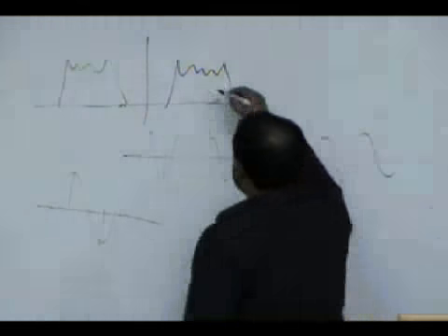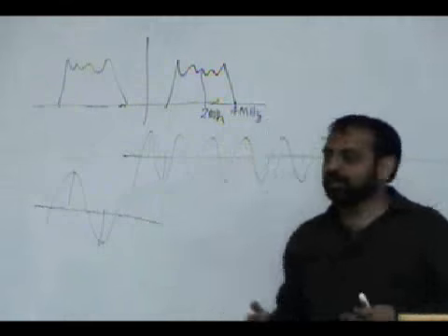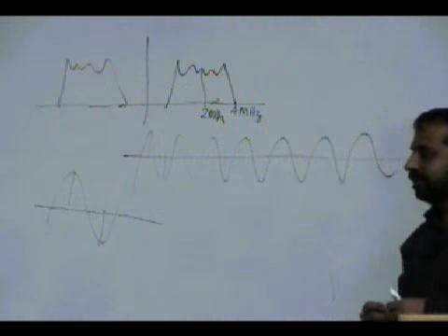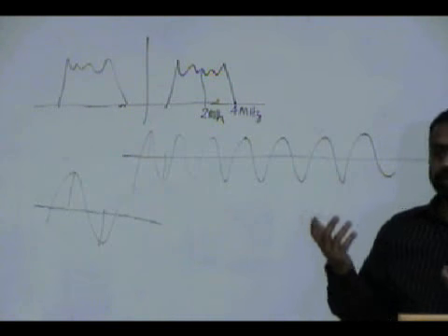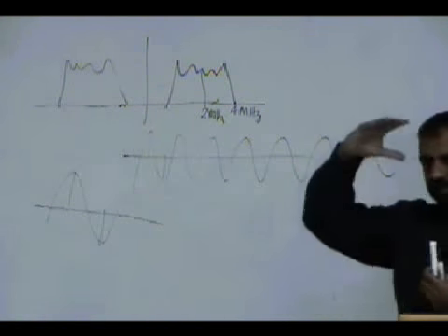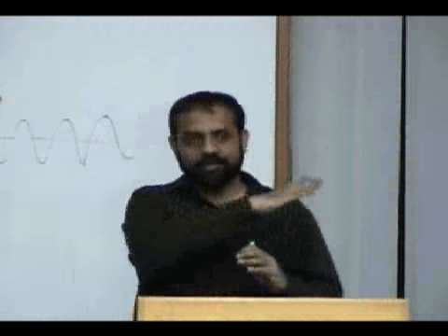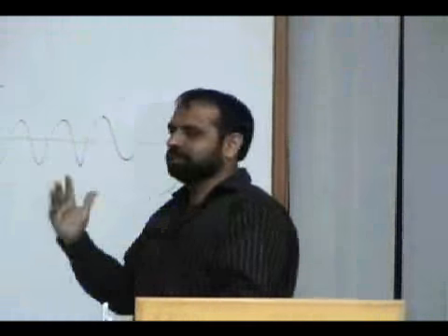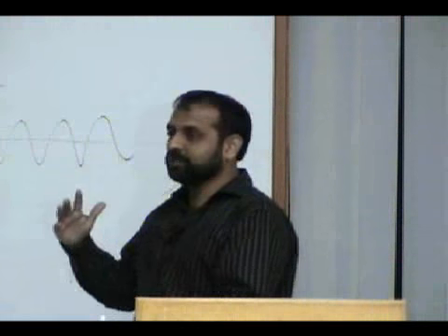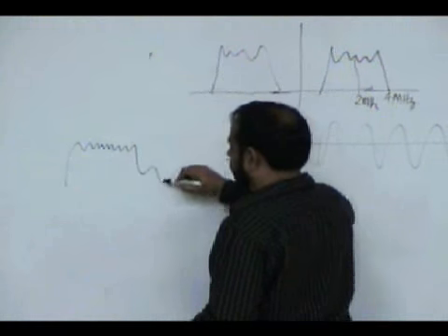What about the frequency content which is at 2 megahertz? How many samples will I have in that? 4. Will it hurt? Obviously not. Let it be. The signal is not disintegrated into cosines. The signal is just a signal which is a combination of all these cosines, with the highest frequency content maybe just riding here in the signal.